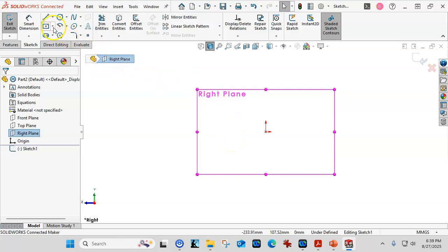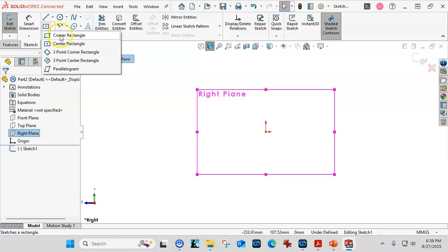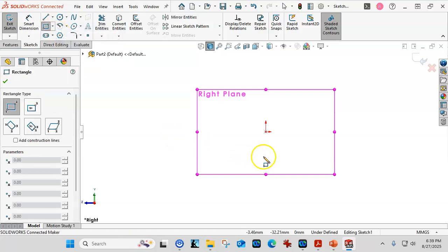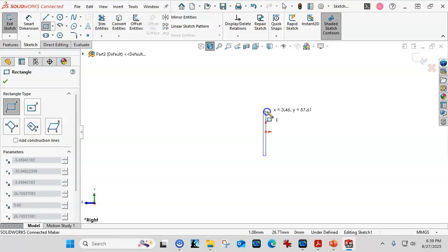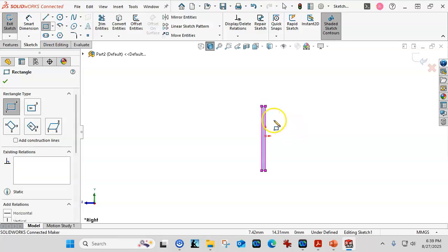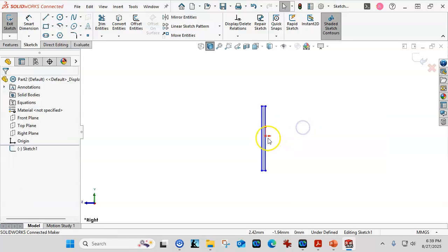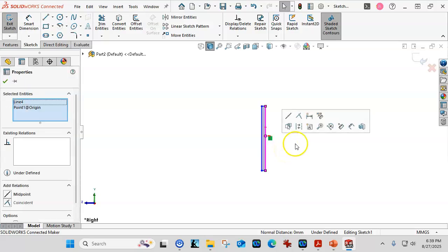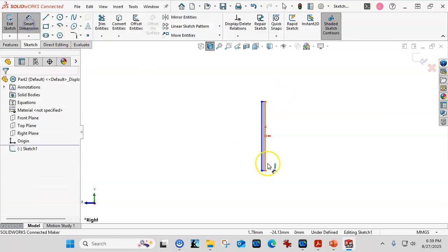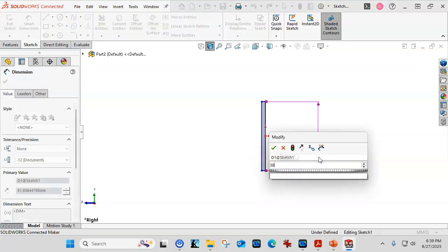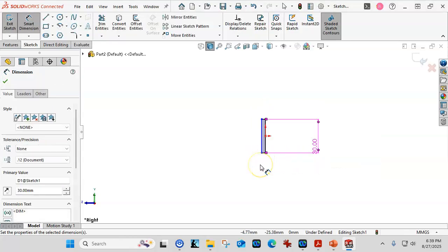is the geometry. Since we're doing contours and regions, let's go ahead and start with the base. Even if I don't generate geometry from this base, I can still utilize it later. It doesn't look like I got a coincident or anything, just the vertical, so I'm going to make that a midpoint. My dimensions then come in at 30, and the height of that somewhere is 5.